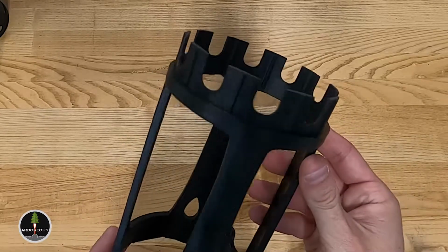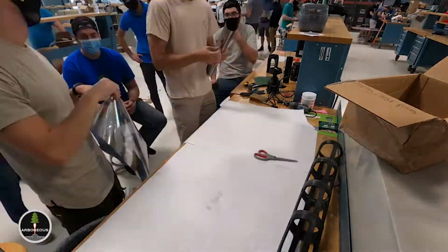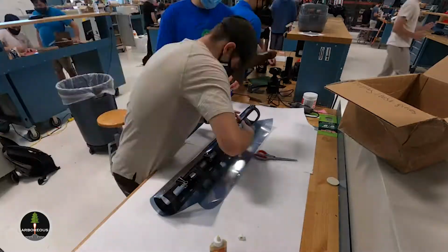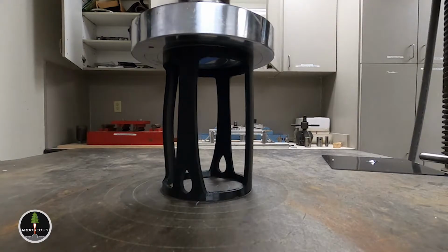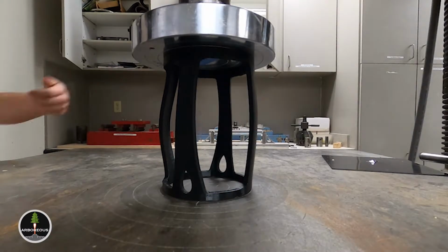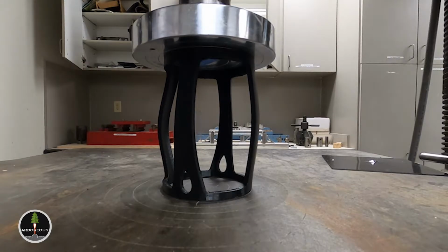Usually, in high-powered rockets, the body tube is a fully monocoque structure made from cardboard, fiberglass, or carbon fiber. In our case, we elected to make a semi-monocoque structure made from 3D printed ABS and wrapped in PVC to act as the aerodynamic skin. This resulted in a 3D printed, mass-optimized part that was able to withstand loads of up to 3 kilonewtons.